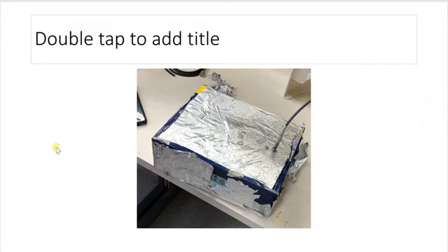I have implemented my cavity resonator as shown here. I didn't wrap the outside of my cavity resonator. It's not intentional, but I bought it like that. I have wrapped the inside of it with aluminum foil and put in an antenna.